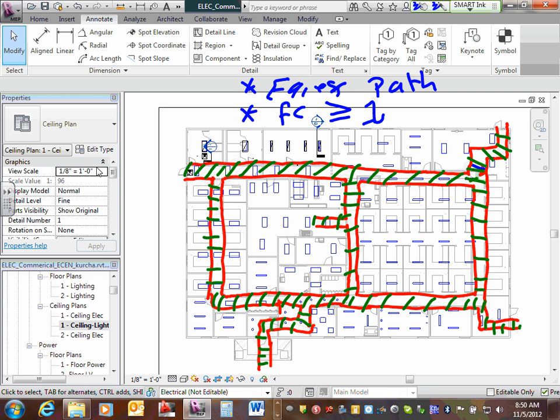Okay, so here's my egress path. Can you guys see the egress path has an outlet from the building almost in every direction? I can exit the building from here, here, here, or here. If you have a commercial building, it must have an access in every wall, right? Anybody knows why? You don't want to trap people in case of a fire. In case of fire, these egress paths and exit signs that you're going to assign right now will lead you through the building to get out of the building. Okay? Cool. So that's my egress path.